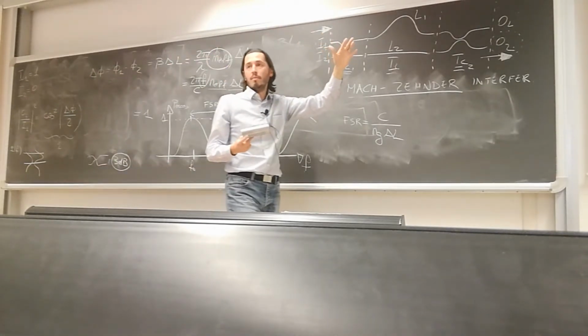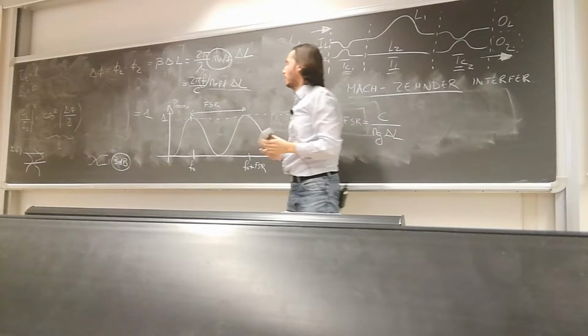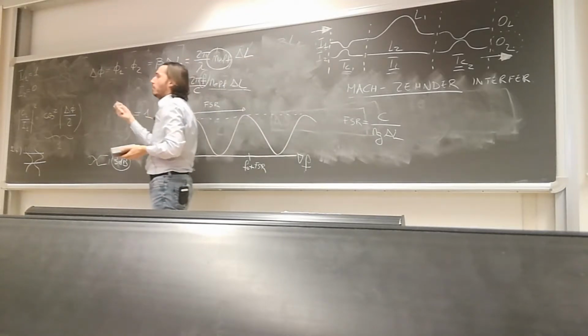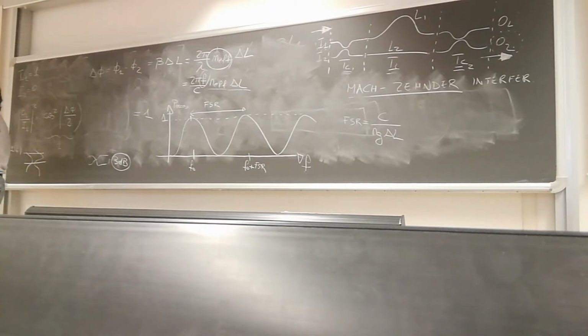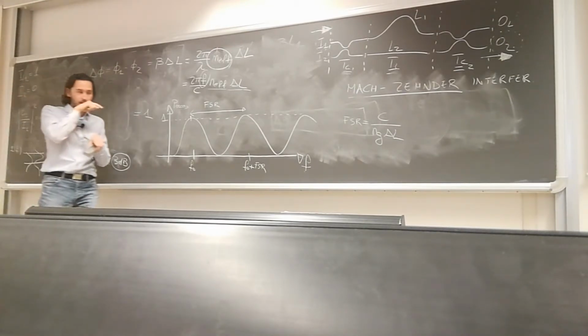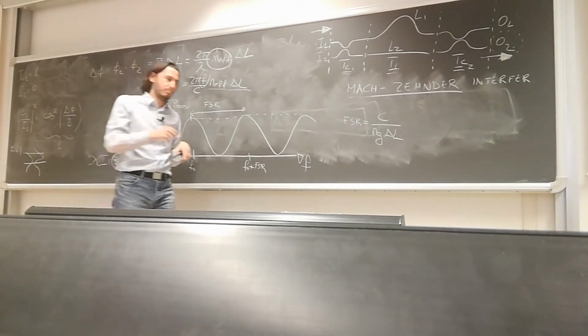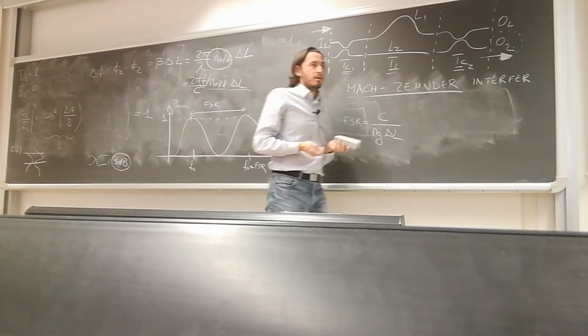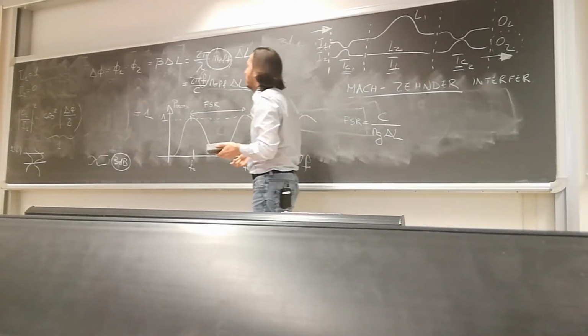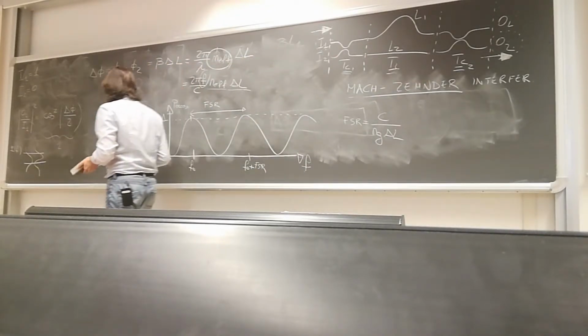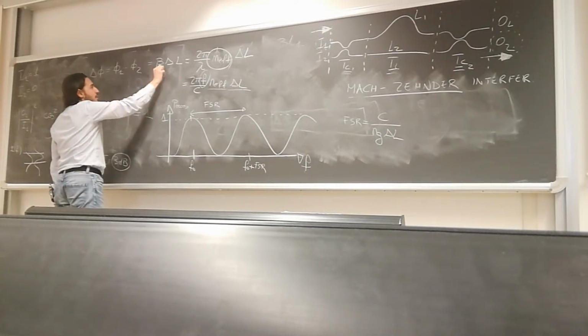Okay? But most of the time, when you have the first TE mode, you have also the first TM mode, because they are very close, so it's very difficult to make such a waveguide. It's possible, but it has some drawbacks. So what you typically have to deal with is a waveguide where actually you have beta TE and beta TM.